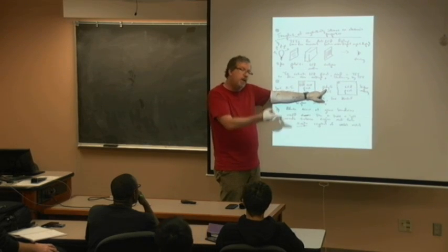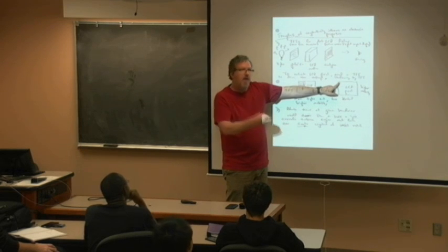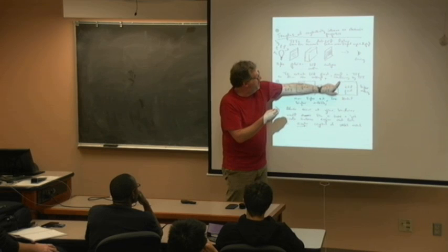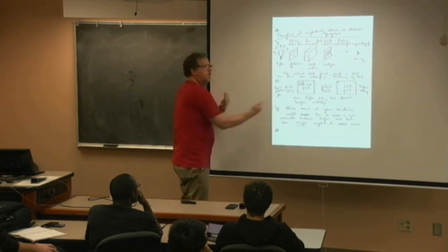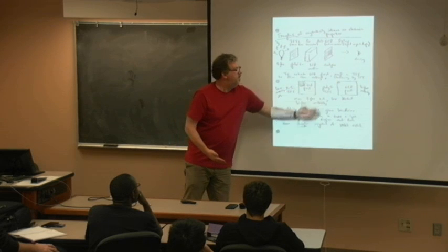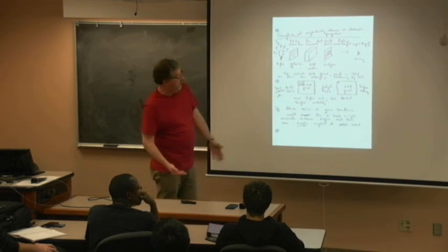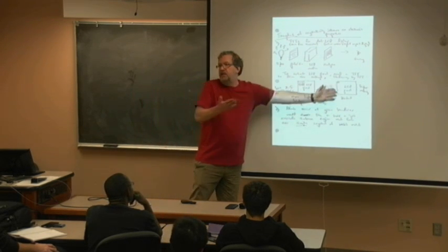So then my mobility goes up, and I can make my transistor smaller and still have enough current drive to drive the whole pixel, right? Because that's a higher mobility, I can make the transistor smaller. So there's a structure property relationship. Better crystallinity, higher mobility, which equates to a higher brightness liquid crystal display.